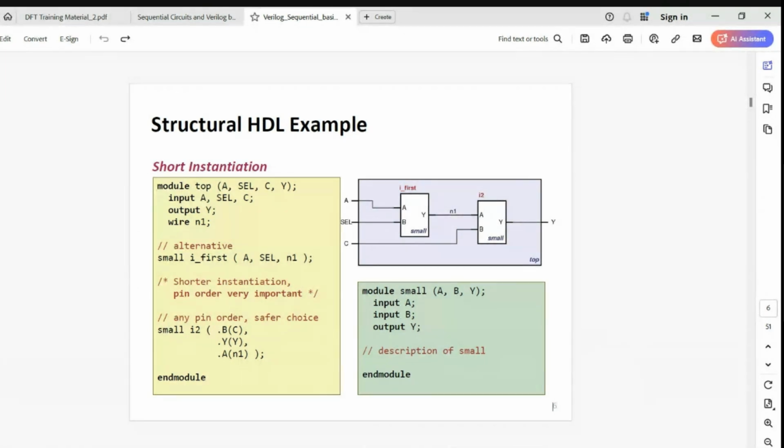So can we write A, B, and Y in that order? So here, if you see, B, Y, A is a zigzag order they have written, right? You can write A, B, Y, or you can start with Y, B, A. Any order is okay. But a proper RTL code, when you start writing and synthesizing, the tool sometimes arranges them as per the order once you synthesize it.